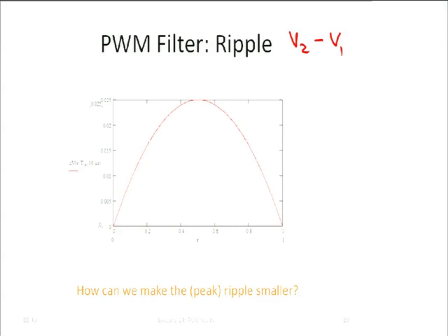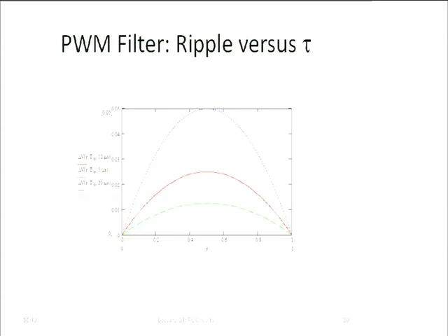One last question. So we analyze this, and for certain values for R and C, we get the ripple characteristic that looks like this. Now, here apparently the ripple is about 2.5% of full scale. What would we have to do if we wanted to cut down the ripple? For example, 10x. Yeah, for example, we could increase the capacitor or the resistor, either of these two. And that's what I did here. I changed the time constant, right? And as I increase the time constant, I go down and my ripple gets smaller.